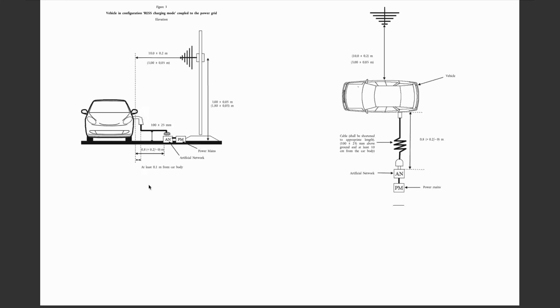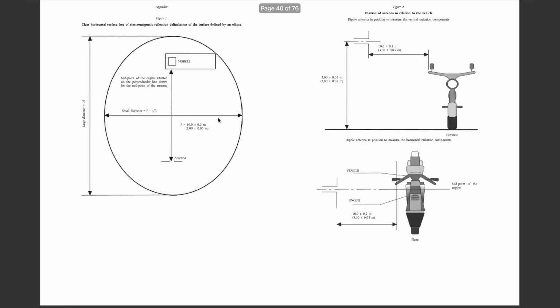Finally, it's worth mentioning that UN10 ECE also specifies testing of the entire vehicle for radiated emissions in accordance with CISPR 25, and this configuration is displayed in this picture here. That's how you would test for radiated emissions of a vehicle, which is not something that I'm going to do. I'm just going to use an electric sub-assembly only, so there's no test setup for this in my case.